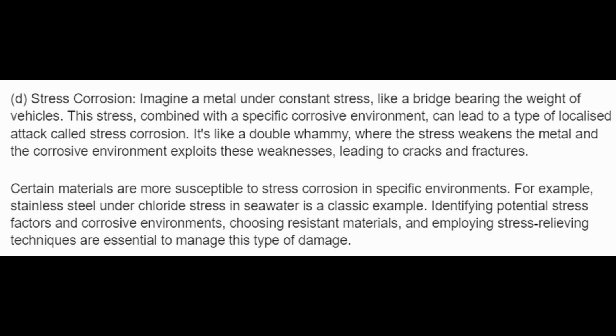D. Stress corrosion. Imagine a metal under constant stress, like a bridge bearing the weight of vehicles. This stress, combined with a specific corrosive environment, can lead to a type of localized attack called stress corrosion. It's like a double whammy, where the stress weakens the metal and the corrosive environment exploits these weaknesses, leading to cracks and fractures. Certain materials are more susceptible to stress corrosion in specific environments.